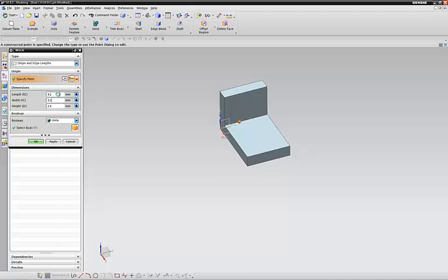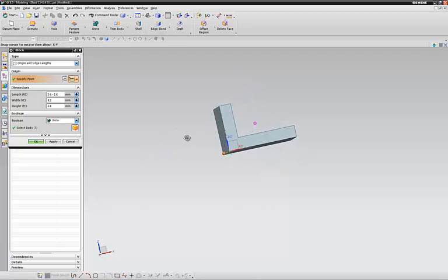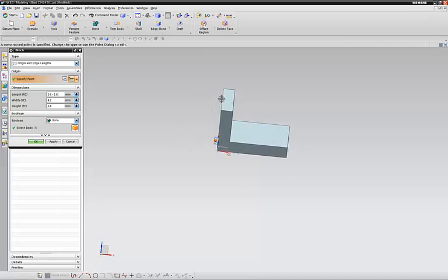And our X is 56 minus 16, because the drawing dimensions it, ooh, my vector's not in the right place, from here to here, and so we minus that 16, so we only extrude from here over, because we're supposed to be starting right here.